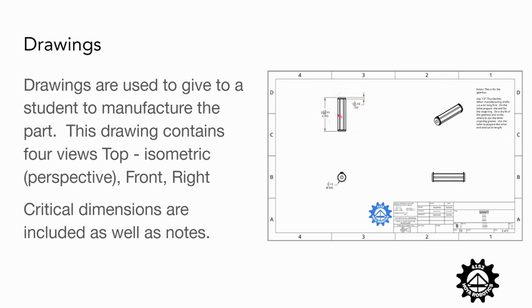What we tend to do is cut it a little bit long, do a dry fit, and then scribe the important things and cut it, because it's easy to go, yes, this is going to be 2 and 13/64, and in reality things might be a little loose or a little tight, and doing a dry fit, we can always cut something shorter, but we can't make it longer.